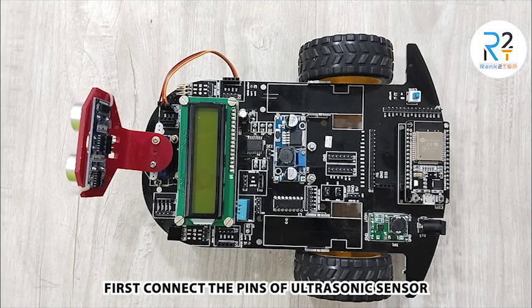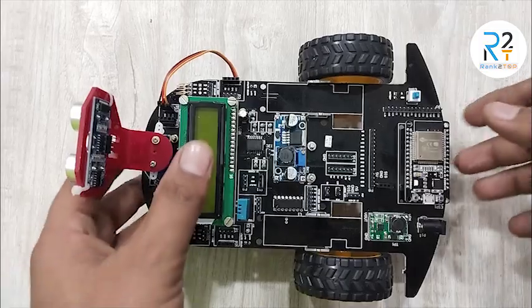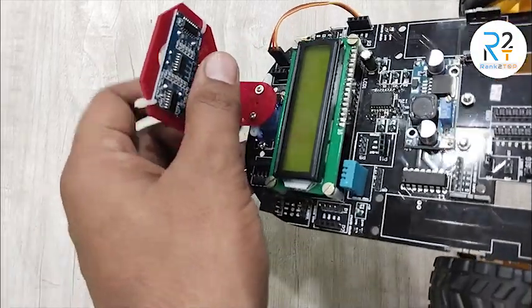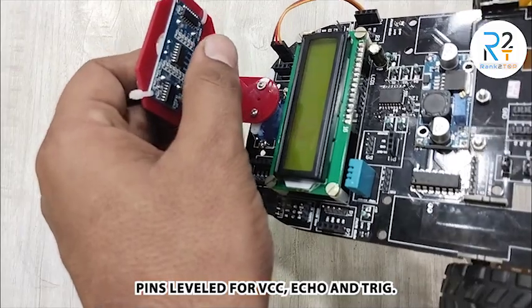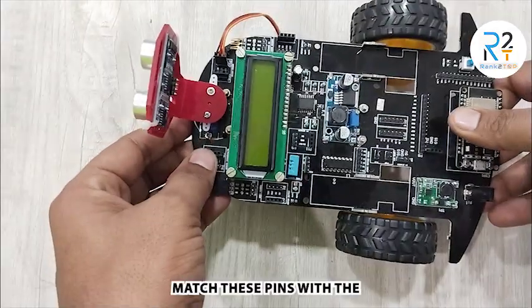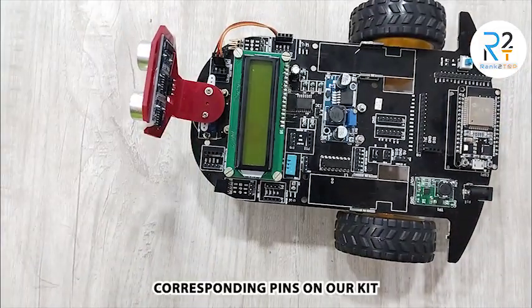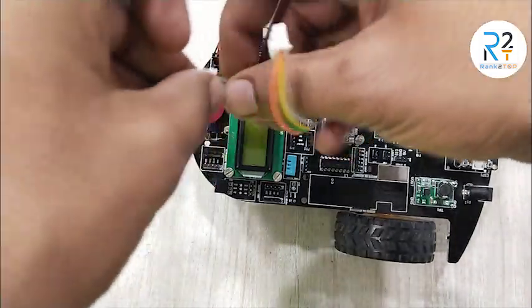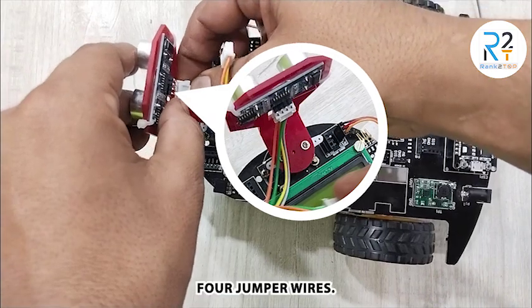First, connect the pins of the ultrasonic sensor. The ultrasonic sensor has pins labeled VCC, echo and trig. Match these pins with the corresponding pins on our kit and connect them with 4 jumper wires.